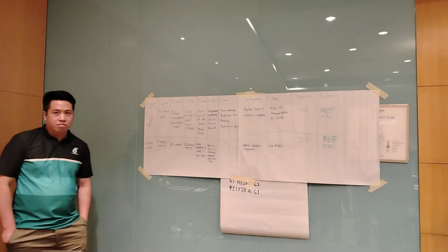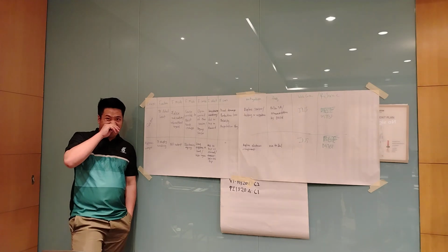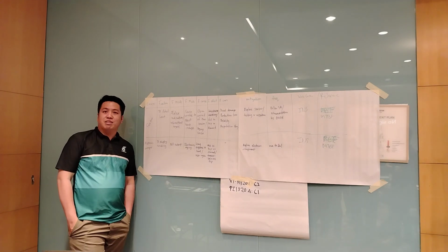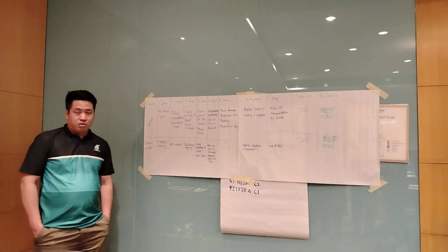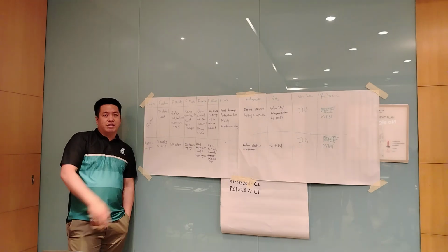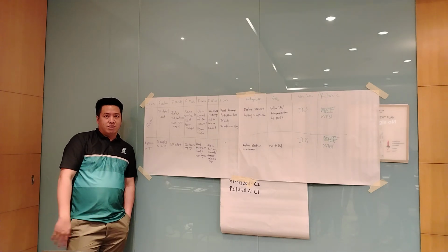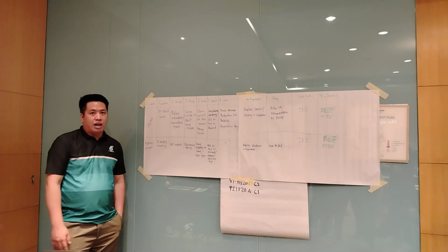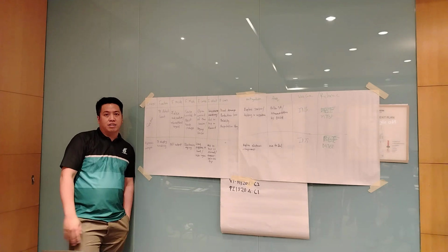Okay, just in the real case, if that happens and it reaches alarm, then what should we do? Bypass or? No, there's no alarm. It trips straight away. Yep. So if you have fire inside the compartment, for sure the temperature will rise up, right? So there's the heat. There are other sensors to detect fire as well. It has UV, it has heat. So it has a voting system.